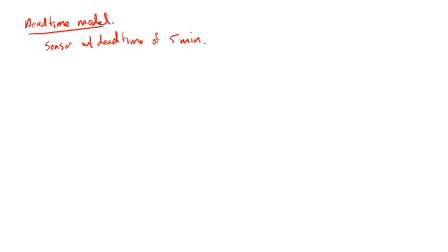So here we can do the same thing. We're going to sketch the dynamic behavior of the sensor with respect to a step input change of, we'll say, 3 degrees. So a step input of 3 degrees C.